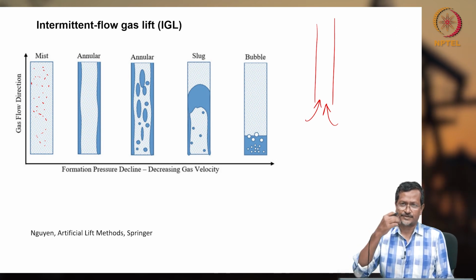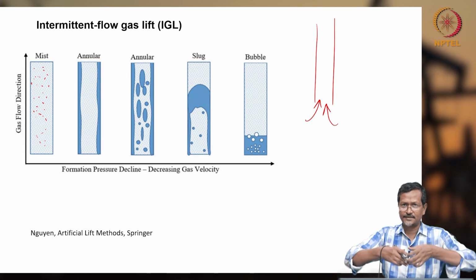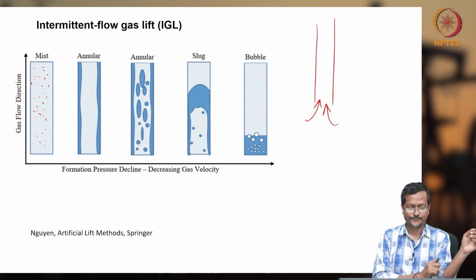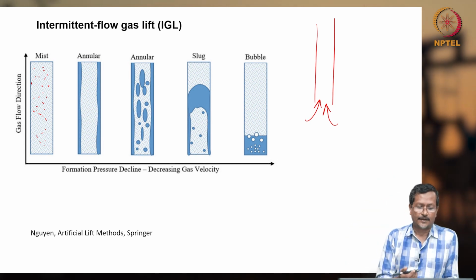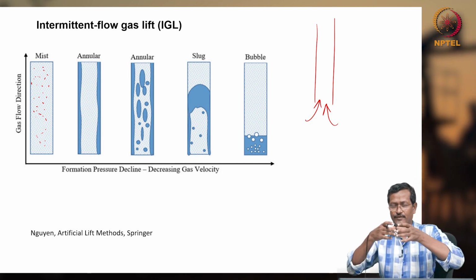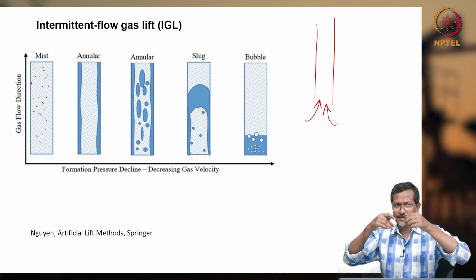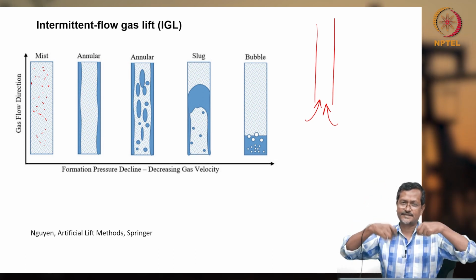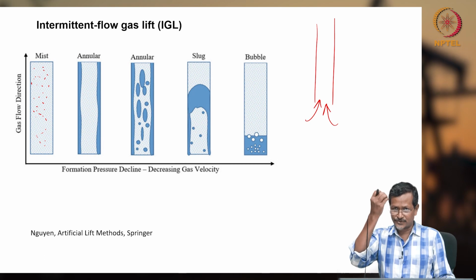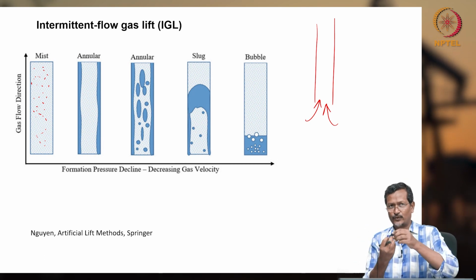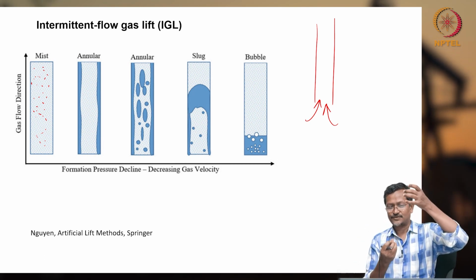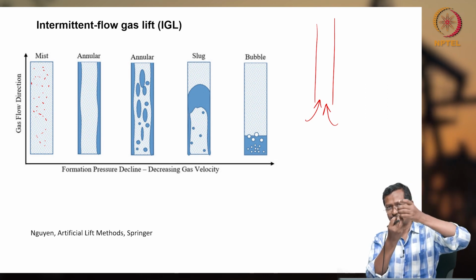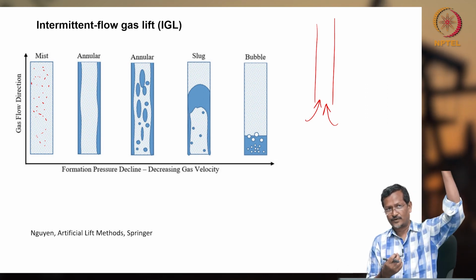So whatever gas velocity there is, the gas will carry this fluid upward. Fluid means liquid. If you reduce this gas velocity, the gas will try to fall back. At very high velocity the gas is going, so the fluid's terminal velocity downward will be lower than the upward velocity of gas, and because of this the fluid will be pulled out of the wellbore.